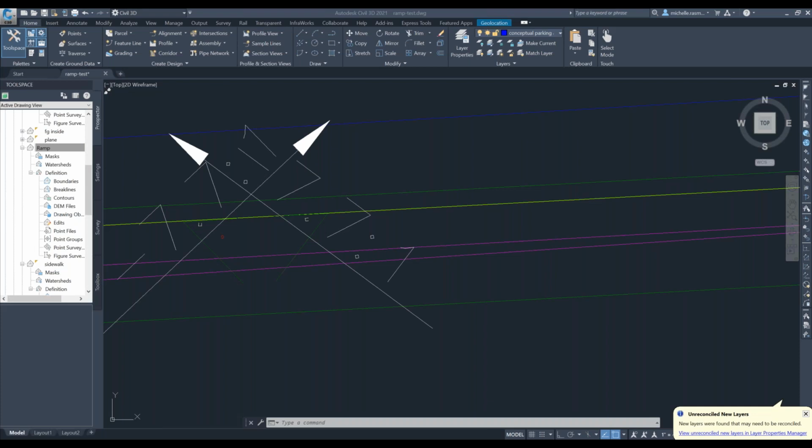So yeah, if the municipality or government agency, whoever's approving your plans, sees that maybe there's water collecting at the ramp you put in, or whatever might need to happen to make that ramp safer, and they say, hey, make these changes, instead of a 10-to-1 slope, let's go to a 12-to-1 slope on those wings. What would you do to accommodate that change?